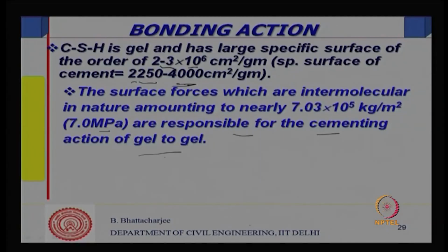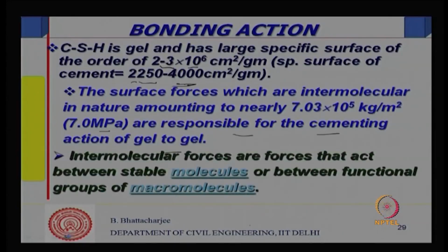So, gel to gel cementing action is because of intermolecular forces, what are called van der Waals forces, and we will come to that. Intermolecular forces are those that act between stable molecules, between functional groups, or between macromolecules. Within the molecule it is covalent or electrovalent bonds, but between molecules there are intermolecular forces, and the gel to gel bond attraction is intermolecular in nature.